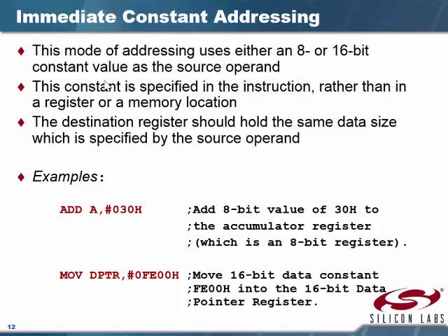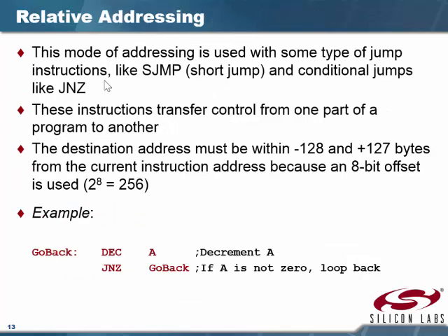But all this simply means, if you see the number sign or hashtag, that's immediate data. If you see the at sign, the A with the long tail, that means that register holds the address of where you're looking. That's indirect addressing.